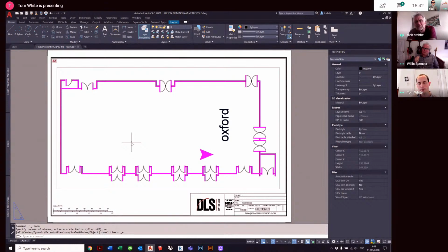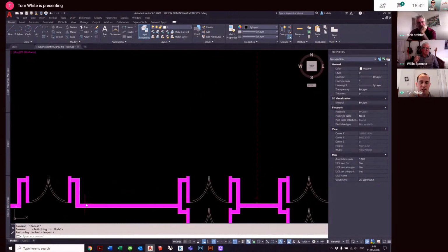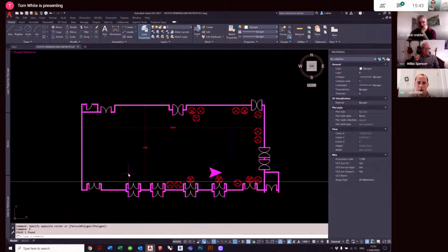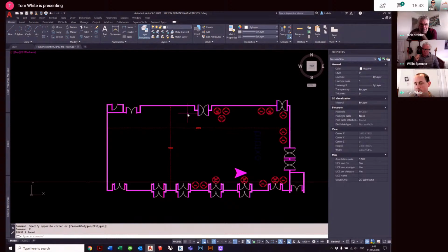Your gut instinct, what sort of tolerances would you work to? A fascinating question. I would have to answer that after seeing a few photographs of the space, because potentially these spaces here might, for example, be low ceilings. So you might design not to go in this at all. So as a consequence, you might want to go 250 millimeters off this line here. So if I do a horizontal construction line, you might want to go 250 millimeters from there, because I've never been to this space and maybe I could look online. But yeah, this might be low ceilings or for other reasons, but something along those lines, Dick.